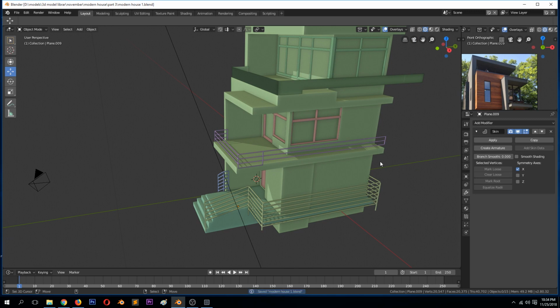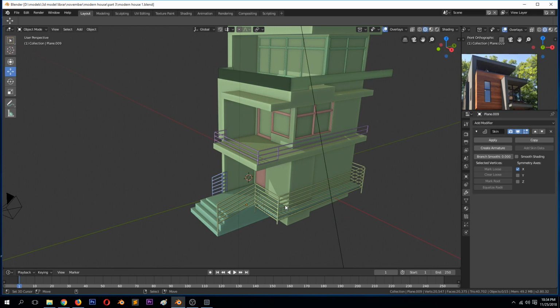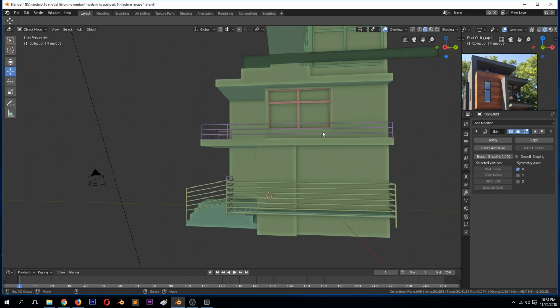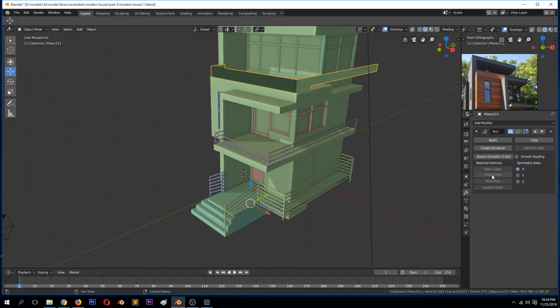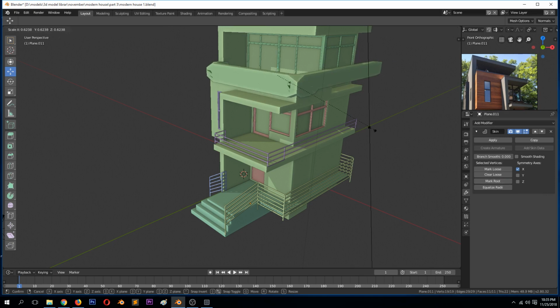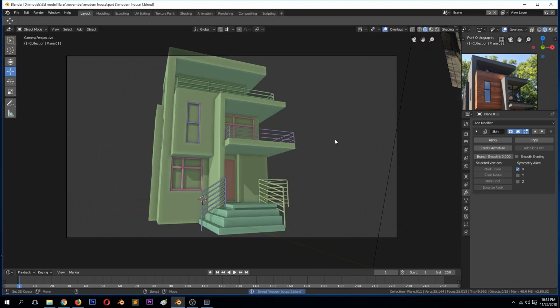It won't render correctly if you don't have them connected. If the meshes are separate, each modifier has to have a root. So we need to select a vertex, mark root like that, Control A. And then we have that.